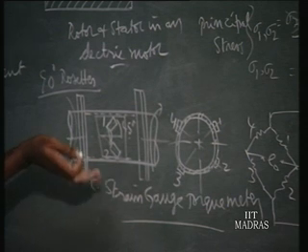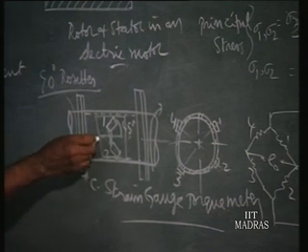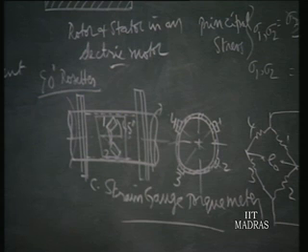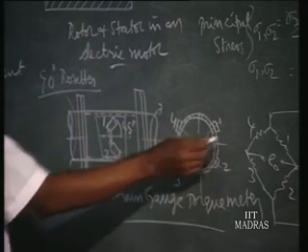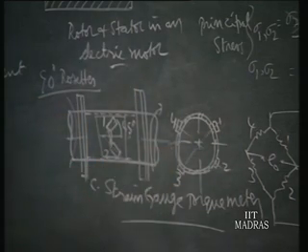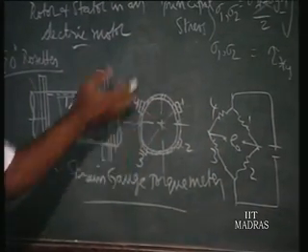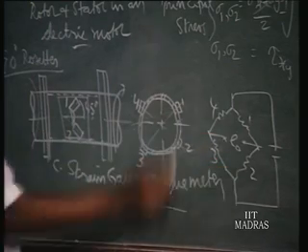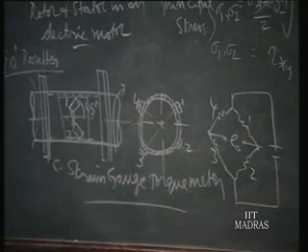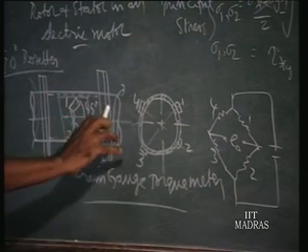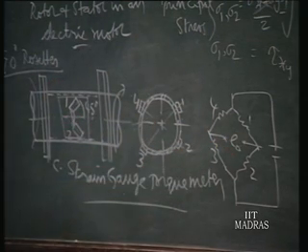So purchase one such rosette, and if the line marked on the shaft and the line on the rosette coincide, we paste it with the cement as supplied by the manufacturer. Then similarly at the diametrically opposite point, we fix these two strain gauges and connect them in the bridge network as per this diagram. So 1 and 3 will be taking up the tensile strain for one particular rotation, and 2 and 4 will be taking up the compressive strain. When the torque is applied, you get an output signal EO proportional to it, and that can be calibrated in terms of torque.